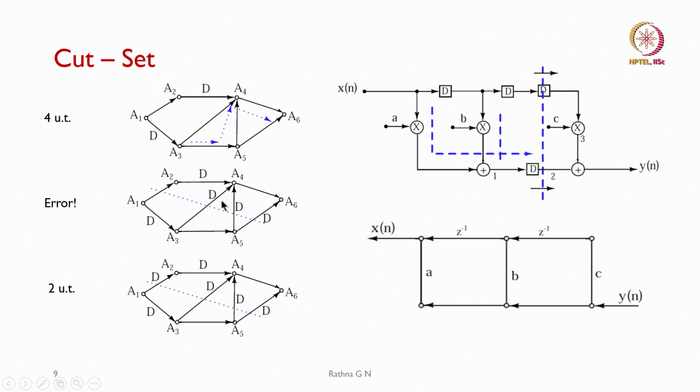So, we have to put a delay line or a buffer, since you are cutting this line also. So, you have to put a delay. All the lines wherever you have cut, you will be having the delay. That is how, in the FIR filter example that we took, which was taking one multiplication and then 2 clock cycles for our addition, we can reduce 1 clock cycle for multiplication and 1 clock cycle for addition by putting the feed forward cut set here and introducing the delay.